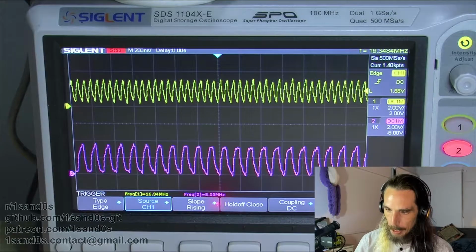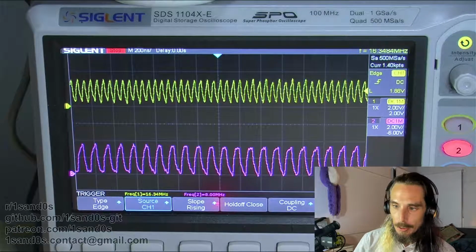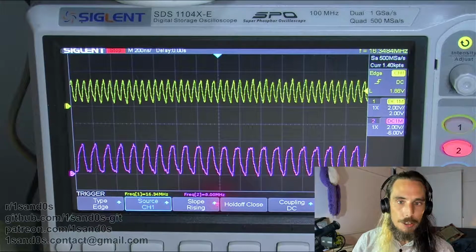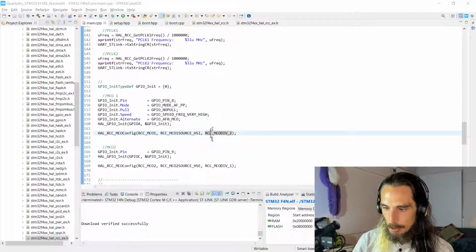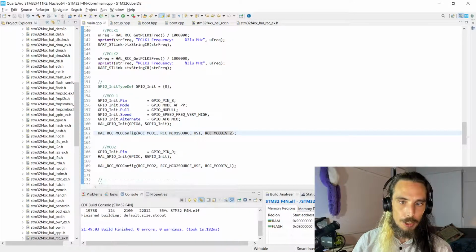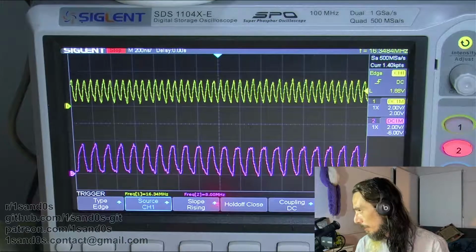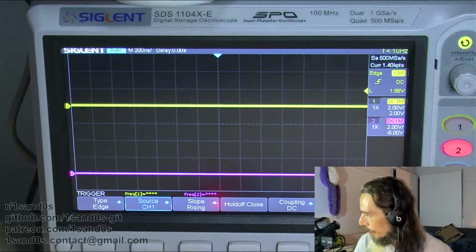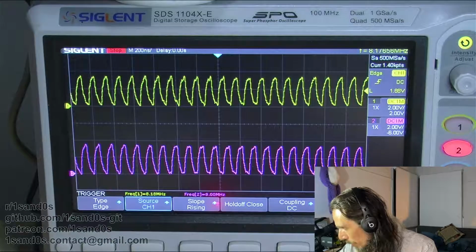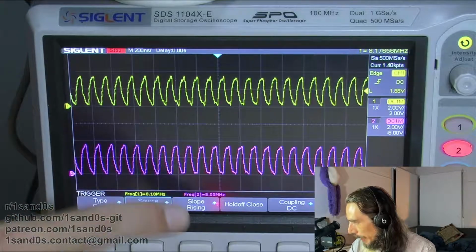Now, just so we can compare them a bit better, let's divide our high-speed internal clock by 2, so that it should be then giving us a clock of 8 megahertz. So to do that, we're just changing our value here to MCO div 2, so that it's dividing it by 2. We'll pop that onto our device, jump back over to our oscilloscope, chuck it back into auto mode. Code's just copying across now. And we can see same thing again. We'll take a single shot, and this clock is slightly high, whereas this one is bang on 8 megahertz.